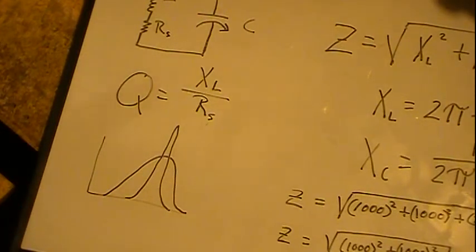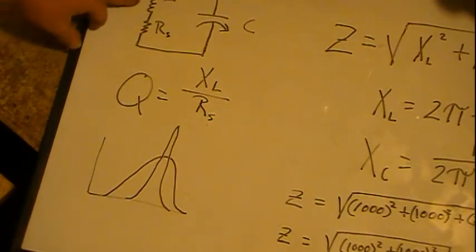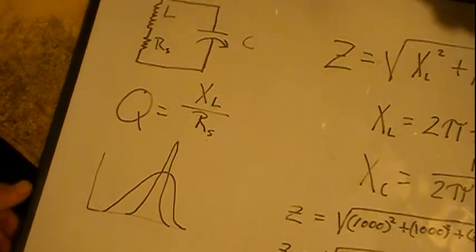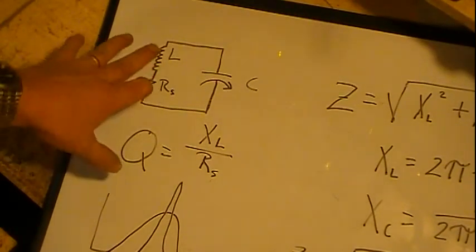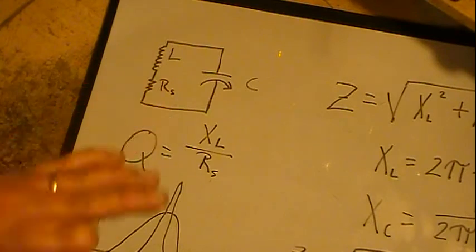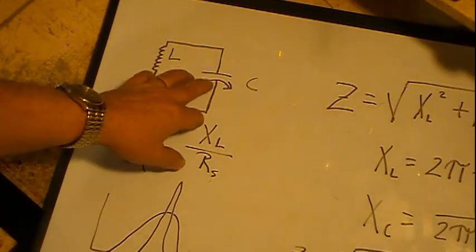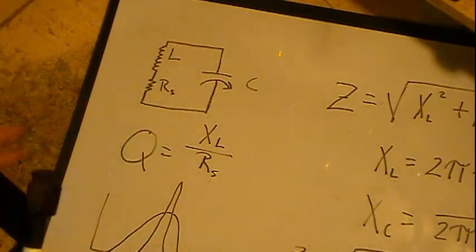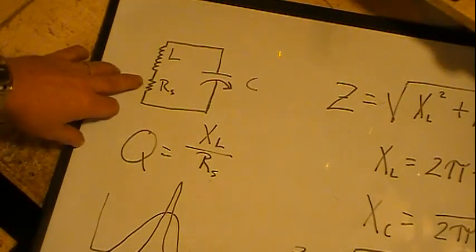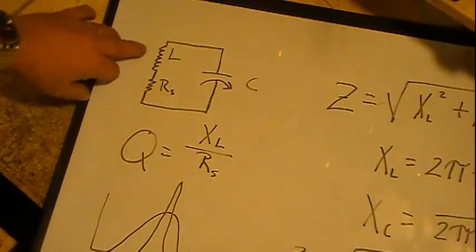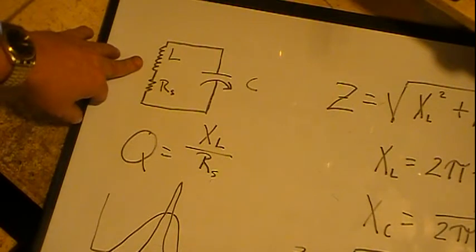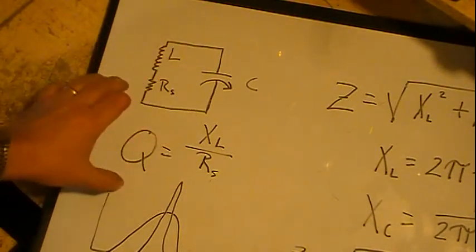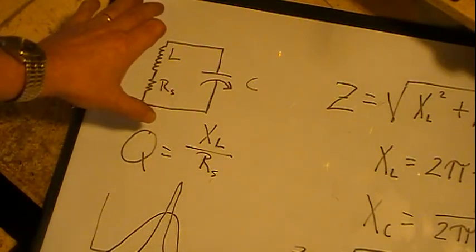Now, if you already pretty well know what the proper inductance was supposed to be for your tank circuit, say an antenna, in order to wind a new coil, and you know what your capacitance is, you can measure it without any problem, and you know what the schematic said for the resistance on that coil, which will be your series resistance, you can figure out the Q of the way it was designed originally.